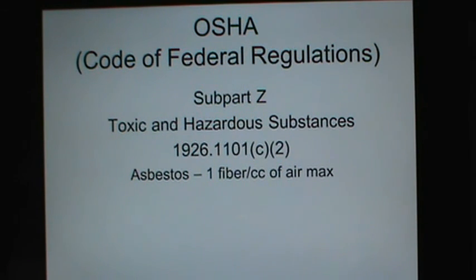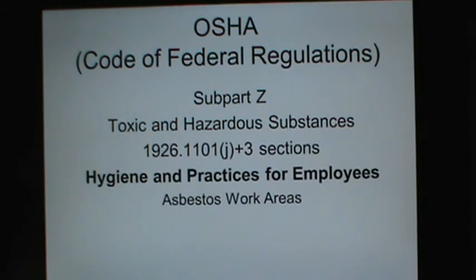It says excursion limit. The employer shall ensure that no employee is exposed to an airborne concentration of asbestos in excess of 1 fiber per cubic centimeter of air, averaged over a sampling period of 30 minutes, as it says. So be aware of that.